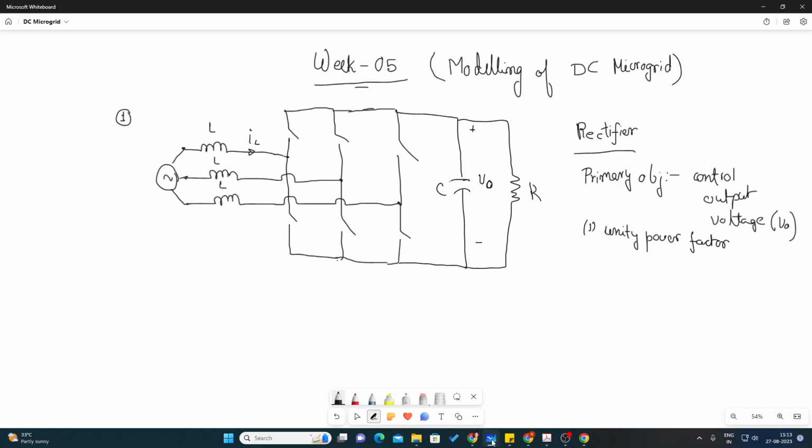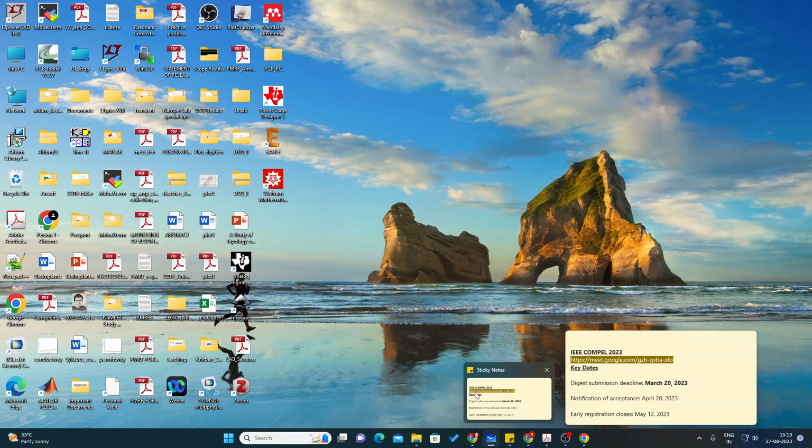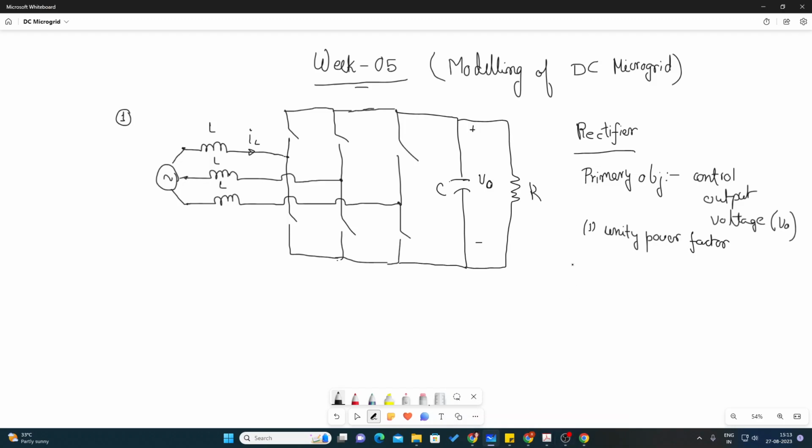So why 10 times? Because in a Bode plot, we essentially check for every decade frequency, right? So 10, then 100. If you can ensure that it's 10 times, then when you consider the outer loop, you can consider the inner loop to have unity gain, so the dynamics can be assumed to be equal to the gain.